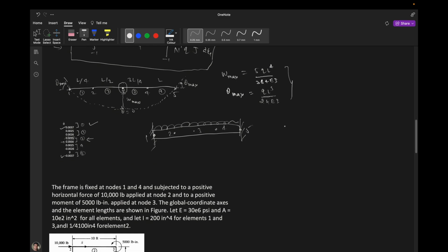For node 1 we already see that W1 and W dash are zeros. These are fixed nodes, which means that the coordinates 1 and 2 are fixed. Here the variables are 3 4 5 6 7 8 and 9 10.